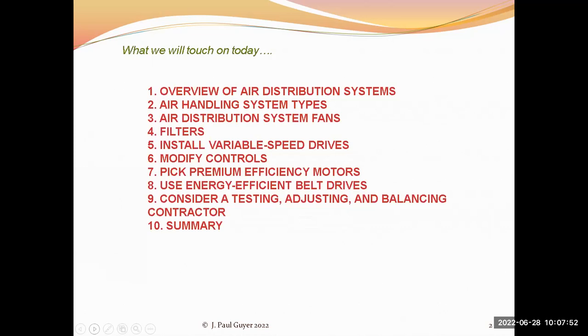Then we'll talk about variable speed drives. One of the industry developments in the last decade or so is the development of variable speed drives, so that when you don't need to have a lot of cooling or heating in a building, you can reduce, with the control system, the speed that the fan is turning at, and that saves energy.